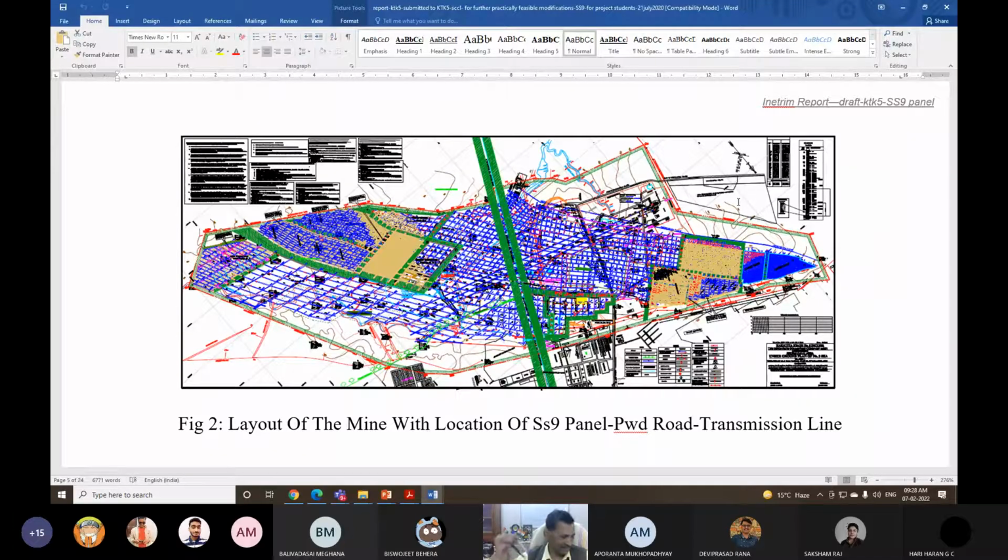So these are the reasons why, when you prepare that, you will have the shape of the pillars not at right angle like this, right? Then it will be something like this, rhombus shaped, right? Now I hope you understood this. Ultimately, these are the dip rise galleries, but these are in the apparent dip. It is not in the true dip. True dip will be very steep.